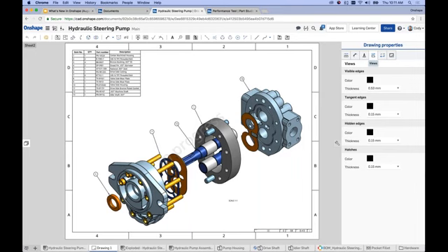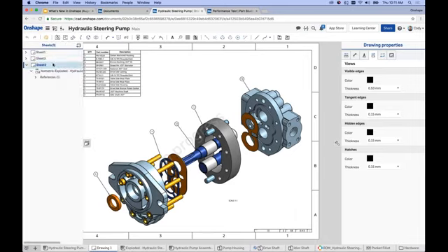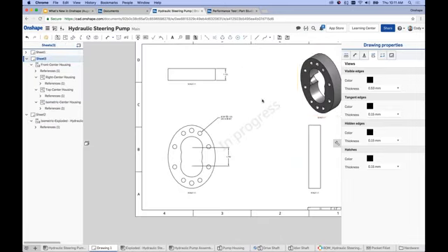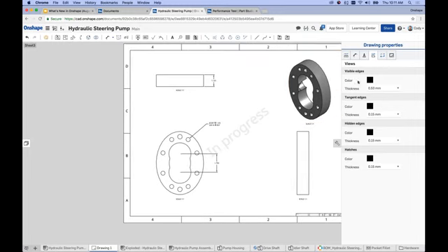Now, the views tab has the thickness, and this is one of the more common questions that I get asked often: how would I go about changing something like the line thickness associated with my drawing? That's under the Views tab, and you'll see thickness as a drop-down. You can choose, for instance, let's make this a little bit thicker, and you can see the line thickness goes up here. Let's go back and set that back. Fairly straightforward. The thing I would stress is you can choose visible edges, tangent edges, hidden edges, or hatches to have different thickness.